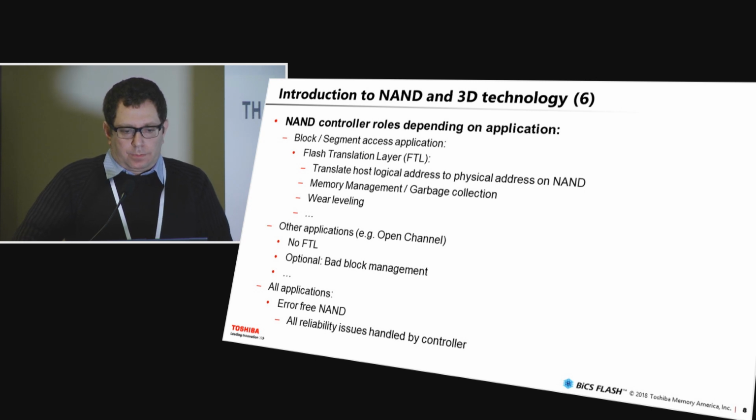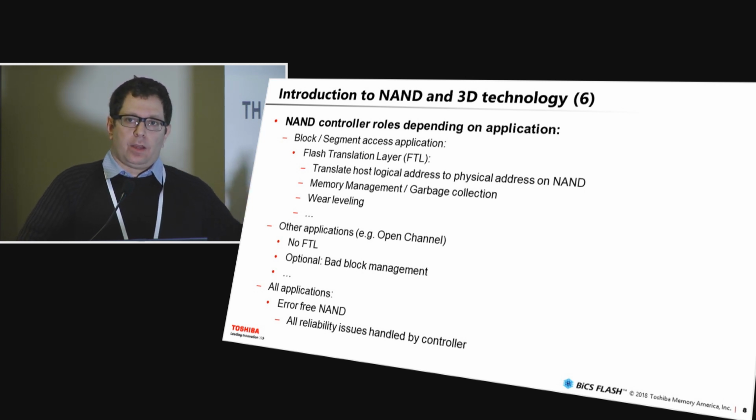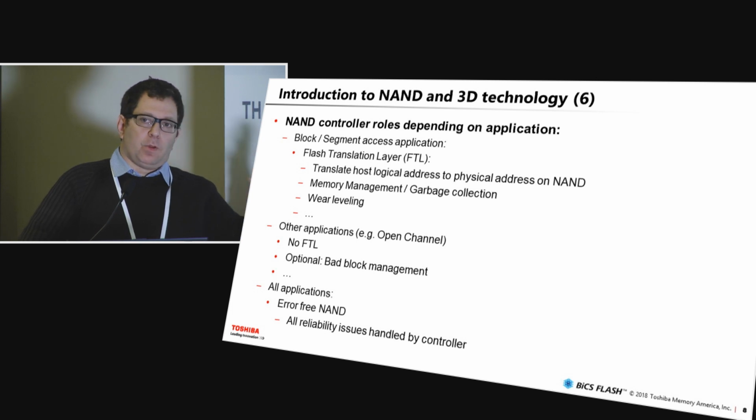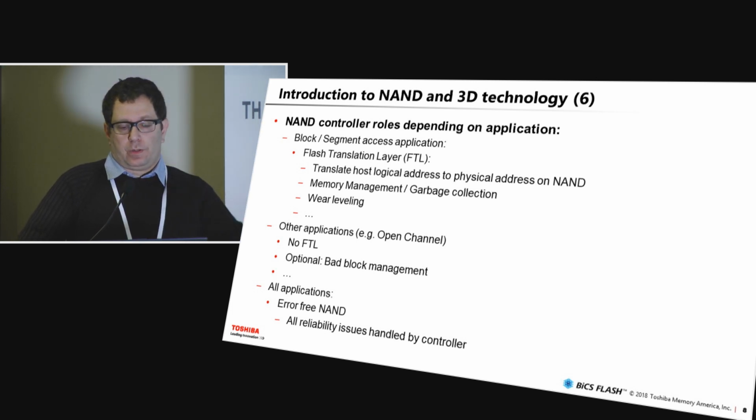So what are the roles of the NAND controller? Well, these depend on the application. For example, with a block type SSD controller, you would have a flash translation layer, which includes a translation from actual logical addresses on the host side to actual physical locations on the NAND side. You'd have memory management and garbage collection operations continually working. You'd have wear leveling, taking blocks which have higher wear, higher program erase cycles, and replacing the data in them with those with lower ones. You also would have bad block management and so forth.